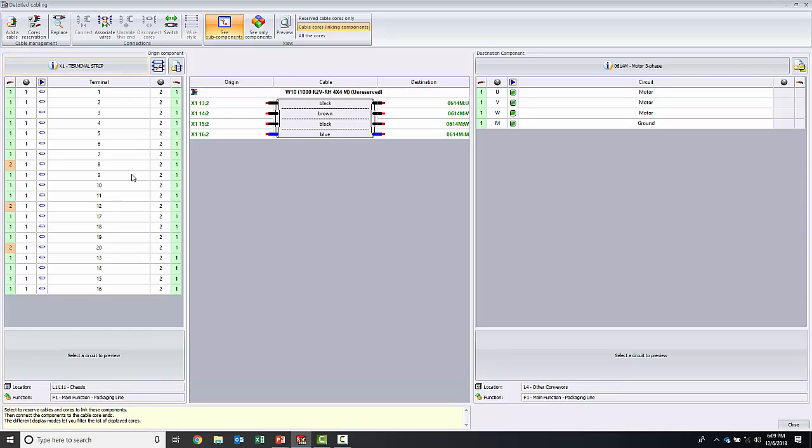Because of that, knowing that I am now connected, yes, I could find it here, but if I click on that, you can see how it flashes and shows me where it's physically connected. So I don't have to think about it, but yet that detailed cabling is embedded in the background to still be able to be used. You can design this way rather than design through a schematic. And that's more for those advanced users that are looking for doing some additional things.